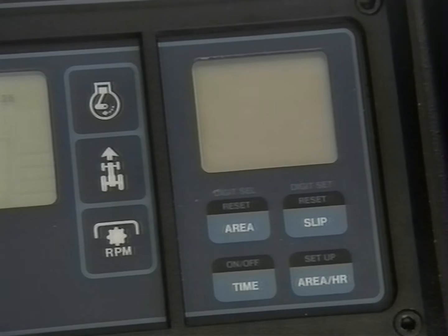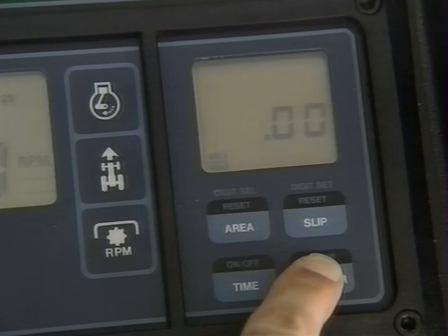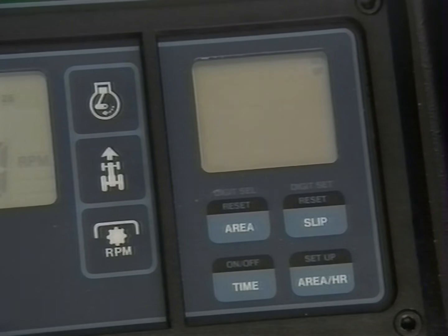Entering information into the tractor performance monitor requires switching to its setup mode. To do this, turn the key start switch to the on position and wait for the screen to display a readout. At this point, the TPM should be in the normal operating mode. Next, press down the setup switch for about 3 seconds. Setup should appear in the upper right-hand corner of the screen.